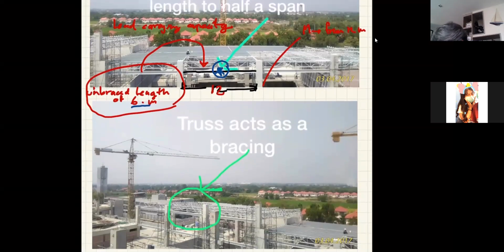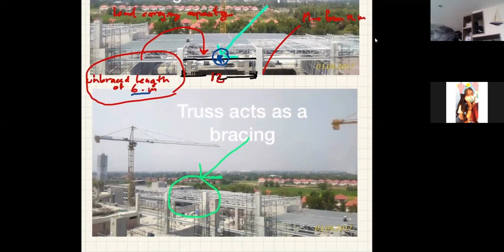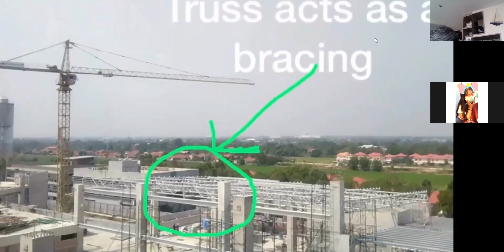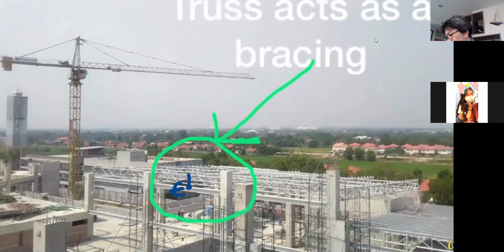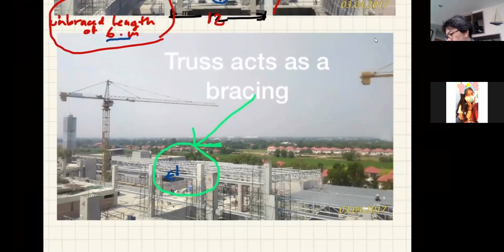This truss will act as a bracing, as you can see, because the truss comes down here, and that is where it is connected to the beam. It should be more than strong enough to help prevent the movement of the beam in the lateral direction, or twisting. And this is the museum that I mentioned yesterday.